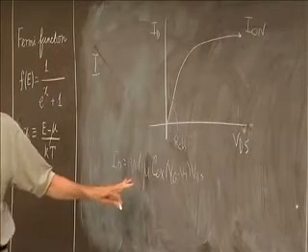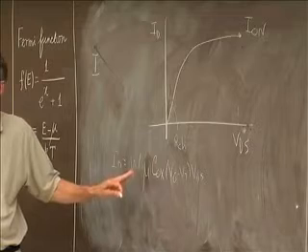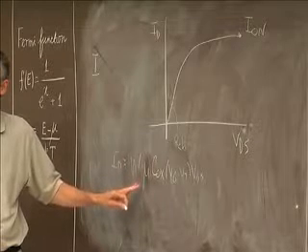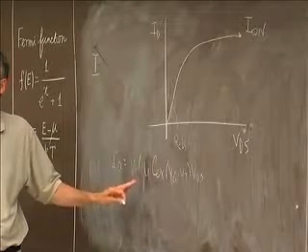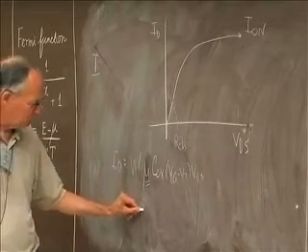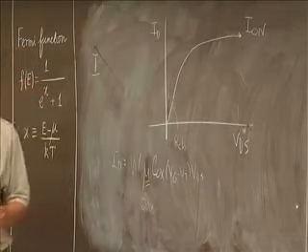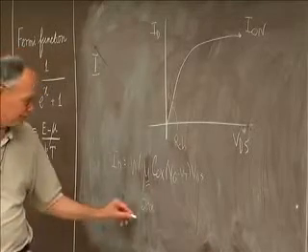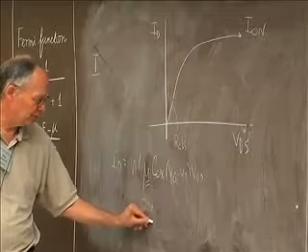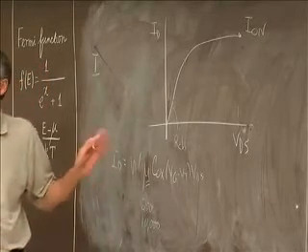So this is a lot of the reason that people were really interested in 3-5 transistors or graphene, because the mobilities are very, very high. They looked at this. Maybe this is 200 centimeters squared per volt second for silicon. Maybe you could get 10,000 on some of these 3-5s. All right, that looks like an enormous boost.